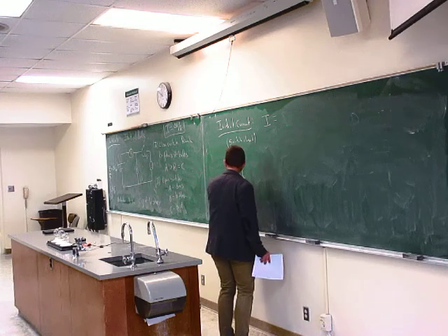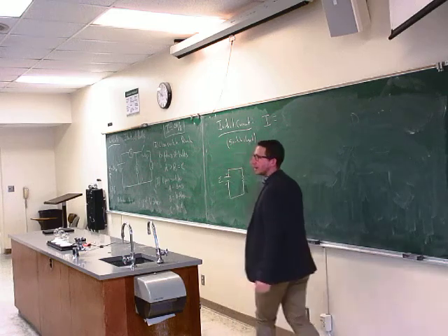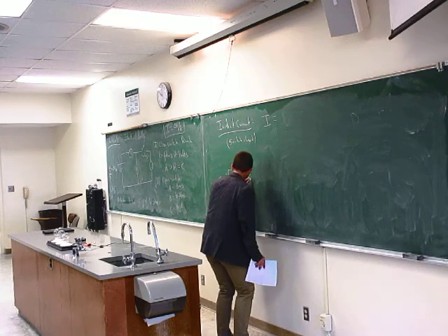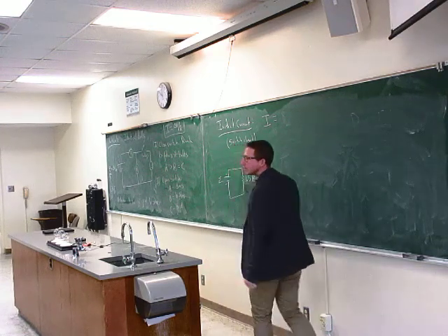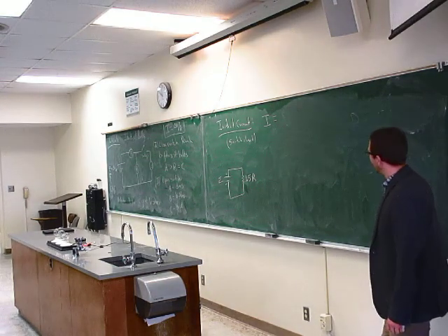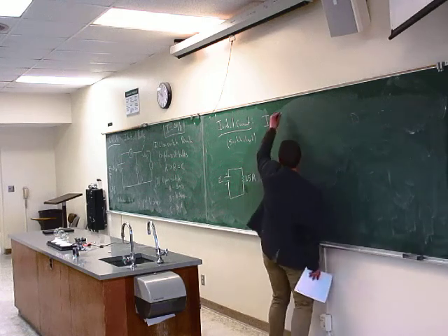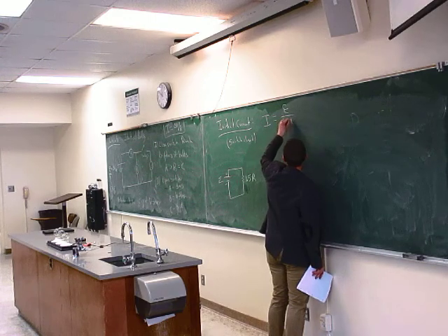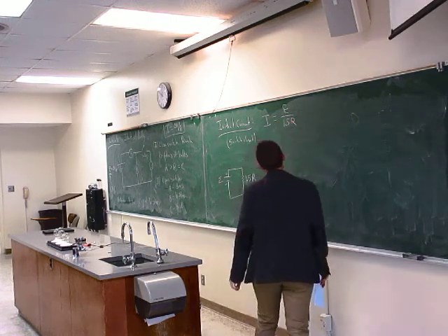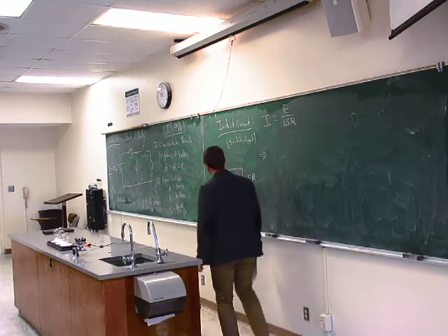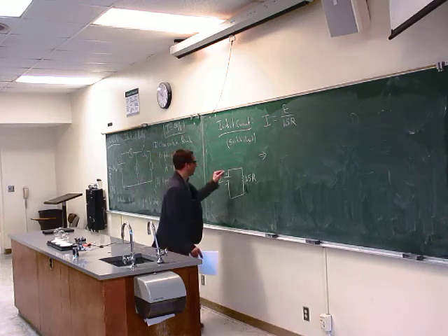And the equivalent resistance here would be, what would the resistance here be? 1.5 R, because I have one resistor in series with two in parallel. So the current would just be epsilon over 1.5 R, which means that's the amount of current that is drawn from the battery.